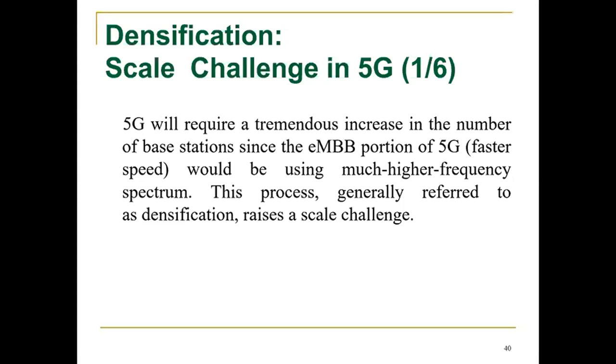Remember, one of the major differences between 5G and the previous 4G and 3G is the spectrum. The spectrum requires a large number of closely spaced towers, which is a very big financial investment. And this is the challenge. We will look in depth at the challenge before moving toward the solution. Definitely, today's discussion is about the solution of this challenge, which is called cloud-centric RAN and software-defined network. So first, the problem is being discussed under these 6 slides. The problem in 5G is called densification, and densification means that due to the high frequency usage, we need closely placed towers, and these closely placed towers are a big investment, and not only a financial challenge but also an environmental challenge. So this is the problem we have discussed so far, densification.